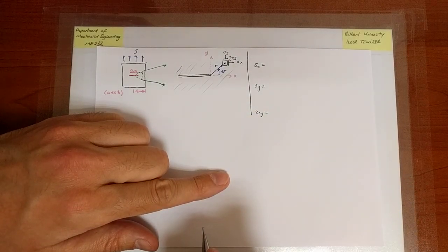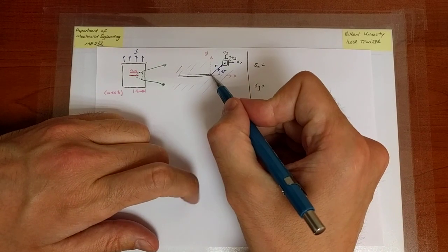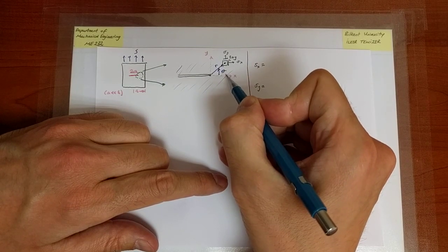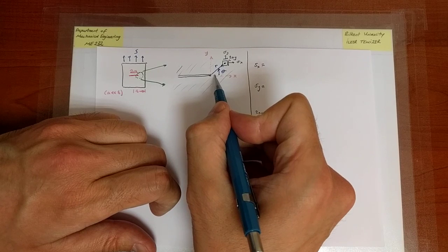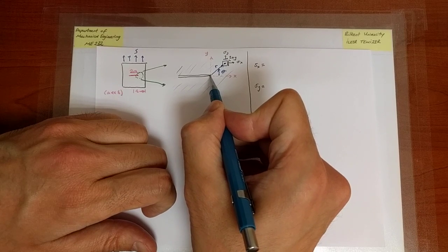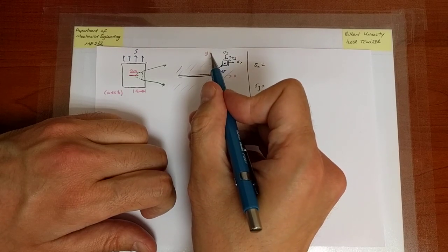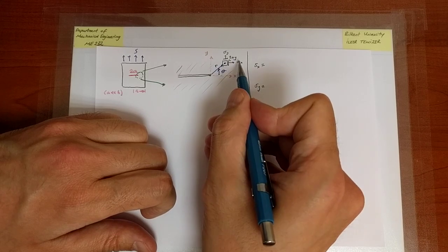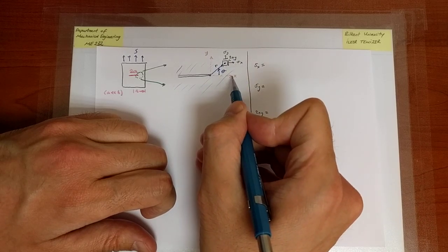Now, it turns out that, first of all, the stress field will depend on r and on the angle. I know it depends on r because if I move along the x-axis, very close to r equals 0, the tip of the crack, sigma y will be infinite, but then it will rapidly decay. And sigma x also changes along that axis.